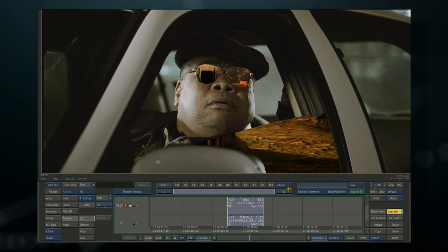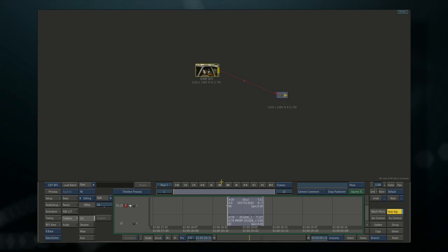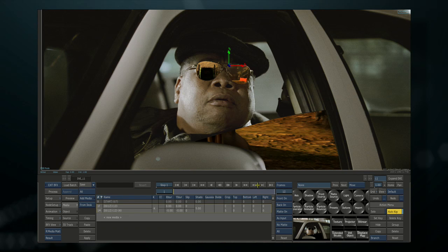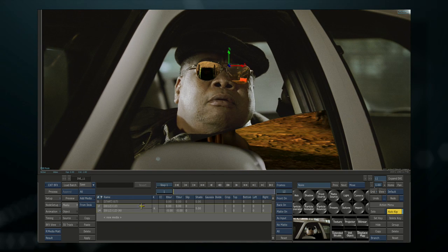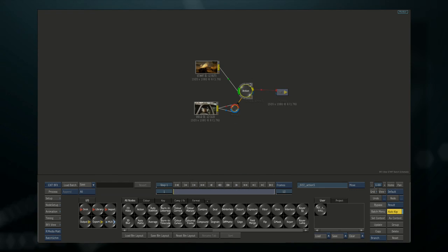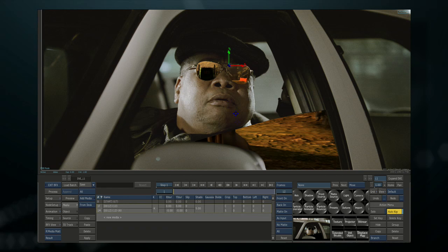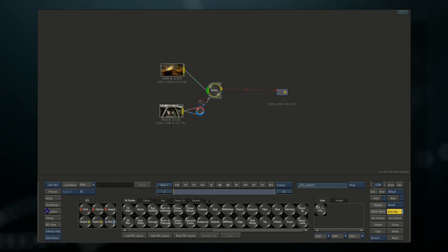I've started some compositing in the player timeline using the soft effects. Why not just take those and promote them out of the timeline but maintain their original relationship? So we've converted the basic axis effect into a more advanced action composite. You can see now I've got that vertical relationship maintained, and I can continue working here in my batch compositing area. Yeah, this is a great example of flexibility, and batch really kind of becomes that creative heart of Flame because you essentially have access to every single tool.